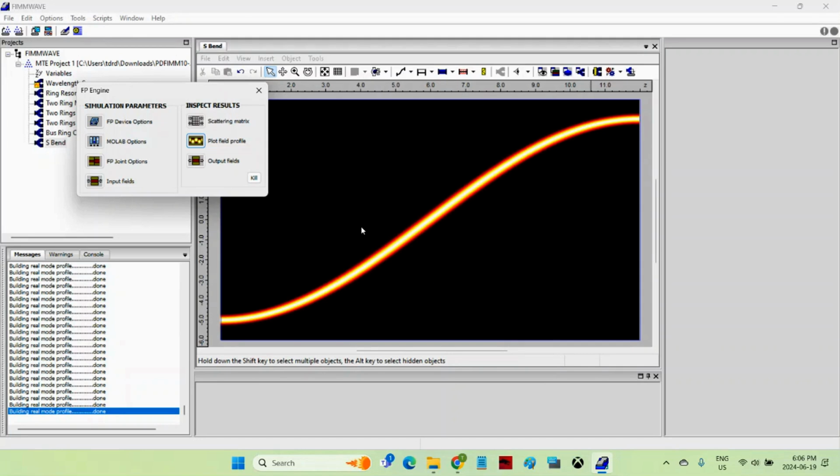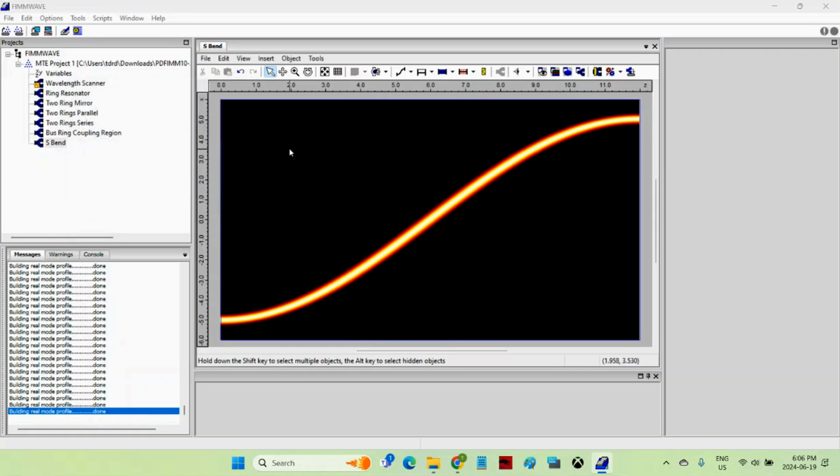Once you've done the design of your PIC or S-bend or waveguide, we can export to GDS2 for fabrication. So MT-FIMMPROP is both a groundbreaking way to model photonic integrated circuits using EME methods, but it's also combining the roles of layout and simulation for those of you who need to design photonic integrated circuits.